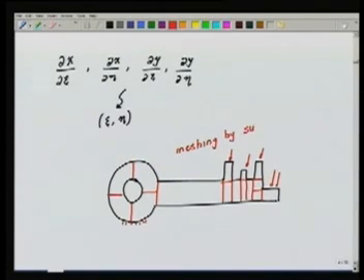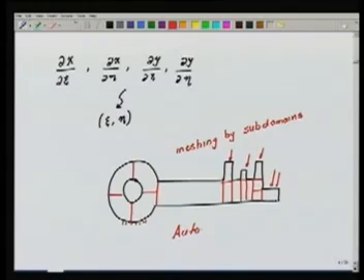Why do you do that? Because this will give you a quite nice looking uniform mesh, and it is not always possible to make the mesh by hand. So you use something called an automatic mesh generator, which takes the domain, the contours of the domain given by you, and gives you a mesh.